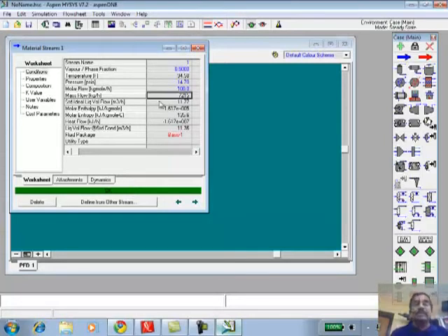Okay? So in fact, it calculated the temperature. Now it changes from blue to black. You cannot change it anymore. So if you want 50% of that feed stream to be in the vapor state, at a pressure of 14.7, at a molar flow rate of 100, then the temperature of the feed stream must be 94.58 in degrees Fahrenheit, and it also shows you in degrees C.